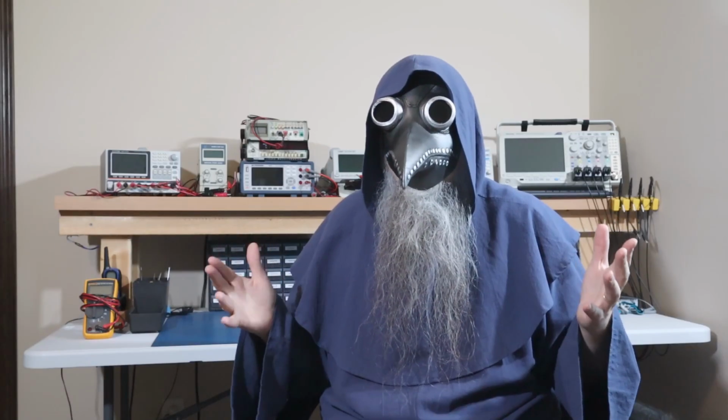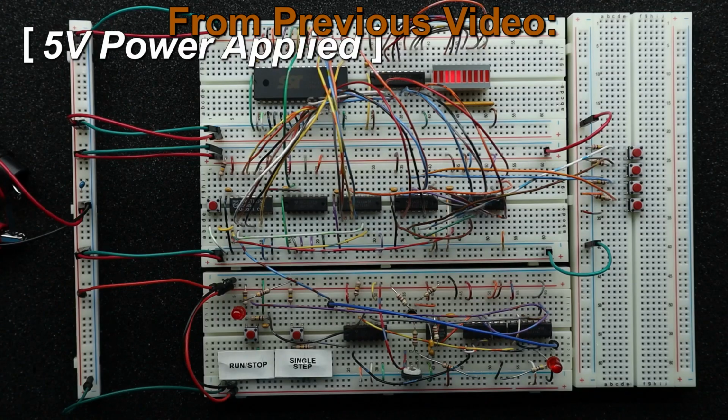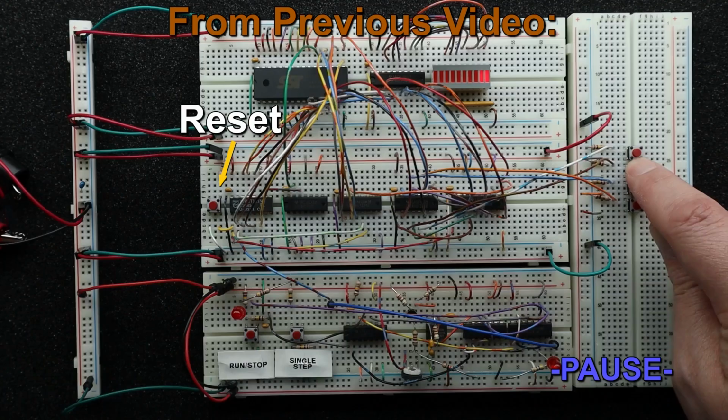But what about the actual hardware? Why did it give us a result of 3? If you'll notice, when I first powered up the CPU, I did not have any of the value input switches pressed. In fact, I'd never pressed a value input switch until after I reset the CPU. When I pressed the reset switch, it cleared out both the instruction pointer and register A. What it also did was disable the decoder.